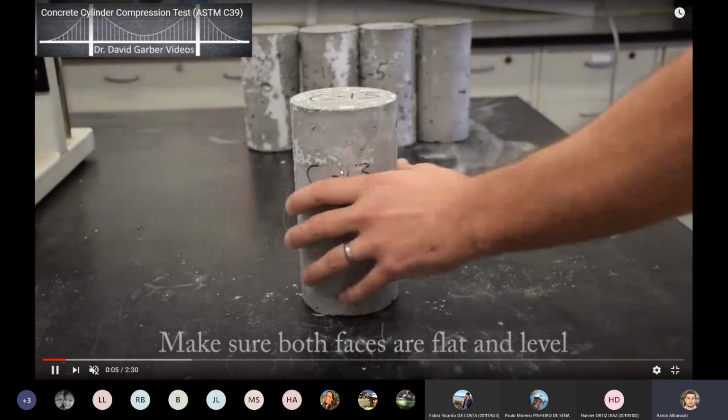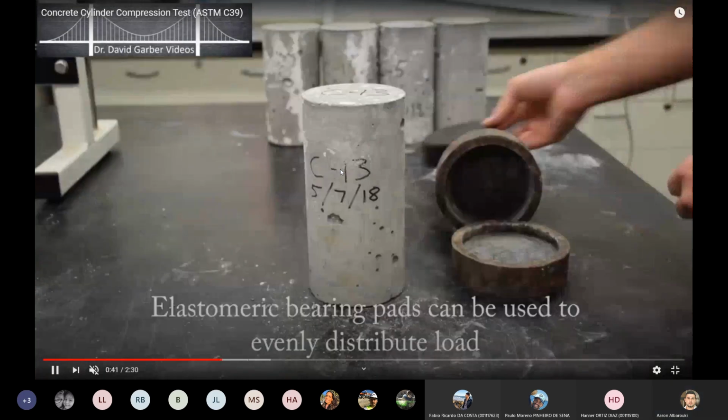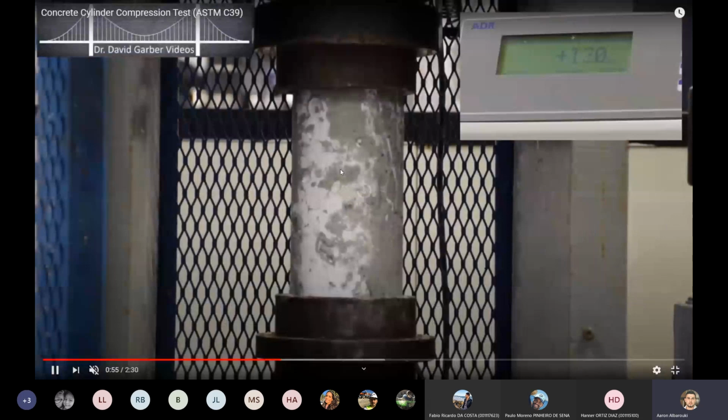So we take a sample, we make that sample sit in a testing jig, and we compress. We add our force here as compressive forces rather than tension forces. And by calculating that force and calculating the cross-section area of that cylinder, that will give us the stress, which is force by area.